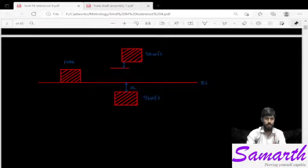That means this is the lower limit of hole and this one is the upper limit of hole. That means the dimension of hole will not be more than this upper limit. This is a tolerable deviation in the dimension of the hole.